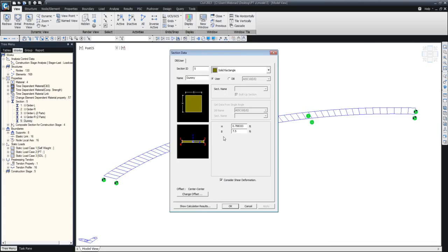So engineers usually try to monitor the bending moment distribution between the two girders by reducing the stiffness, and when they come to a point that the bending moment in an individual girder is not reducing after a certain point, that means it is not being shared any longer with the adjacent girders, they come to this limit on the width. So this is the standard practice.